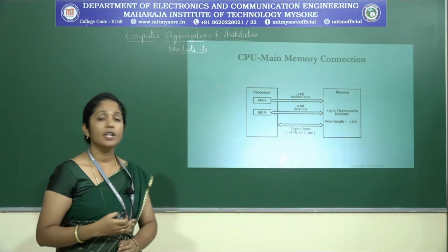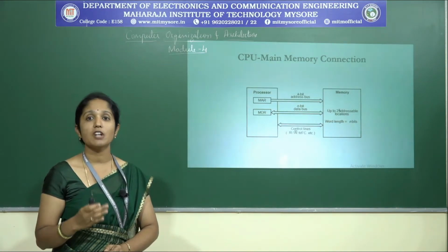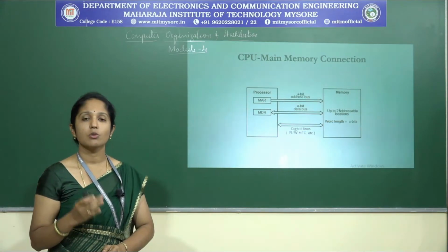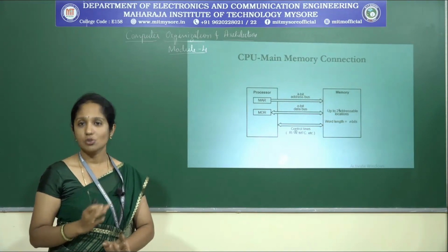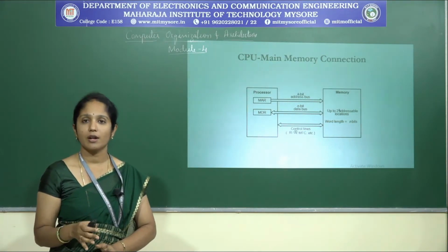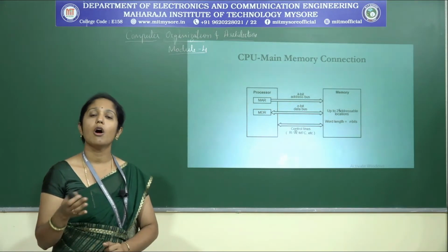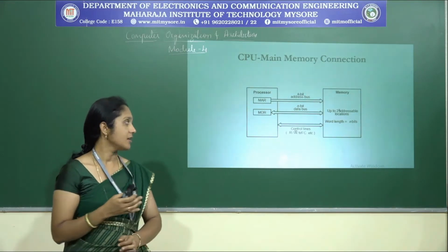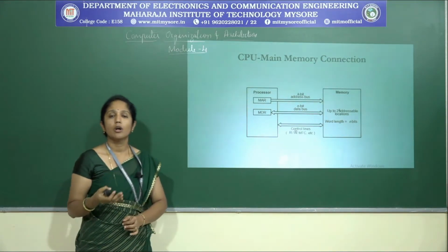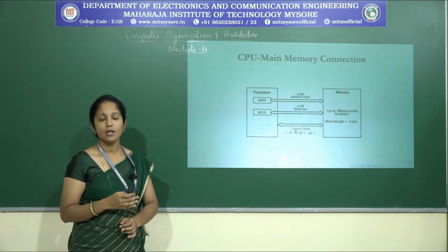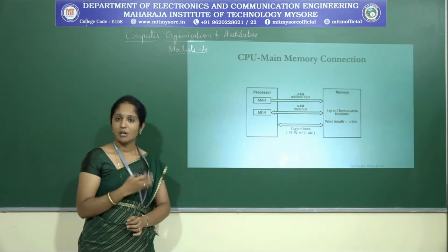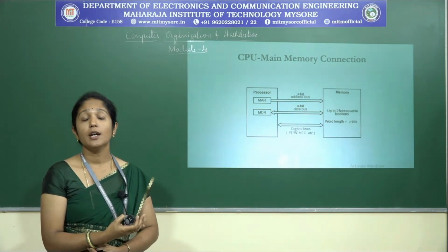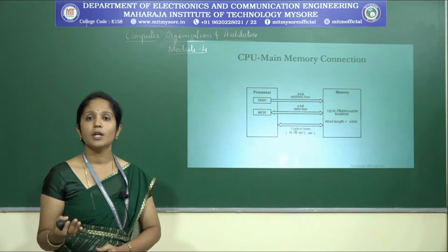MFC is the memory function complete signal, to indicate that the operation is over, whether it is a write operation or a read operation. Once the operation is completed, this will be asserted so that the processor can know the function has been completed. This control line can also be used to indicate how many bytes of data need to be transferred.